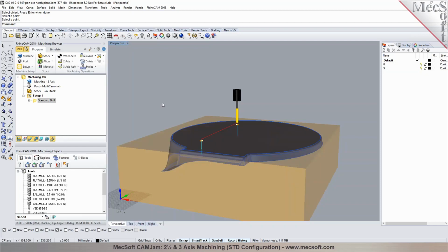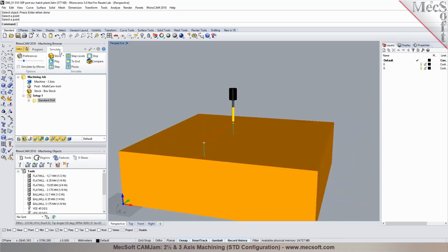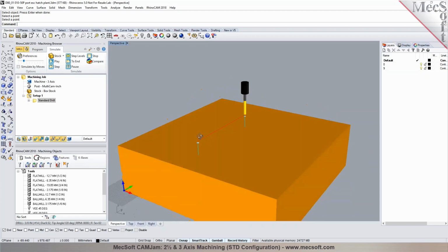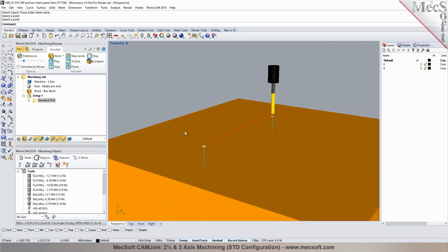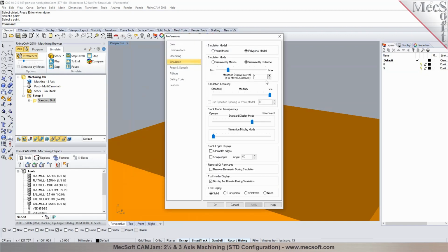Is that live speed? No, it is not. It's basically a speed for the simulation. That's independent of the speed that you're going to be seeing. Does it do live speed at all? We don't do it at the actual cutting feed rate of the machine. So we don't simulate the speed at which the machine cuts it. We have a machine tool simulation in one of the higher configurations, but again, the feeds and speeds that you put in is just getting output in the posted code. It's not used for the purpose of simulation.